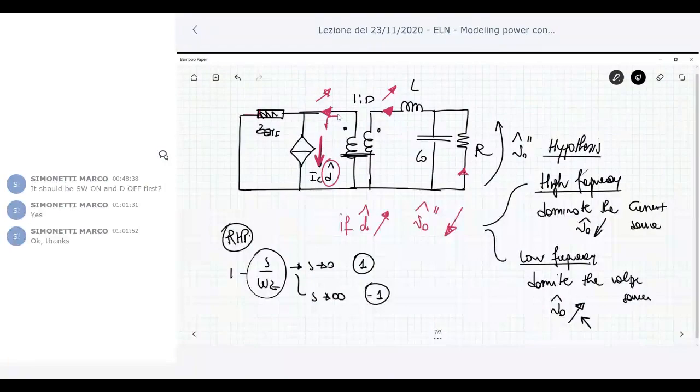Is this a really important problem? Typically this does not happen so often. The impedance of the EMI filter placed at the input rarely induces instability of your converter. What most often occurs is that you can have a phase margin of your closed loop system which is lower than what you are expecting, due to this problem. But in very few situations this can lead to instability.